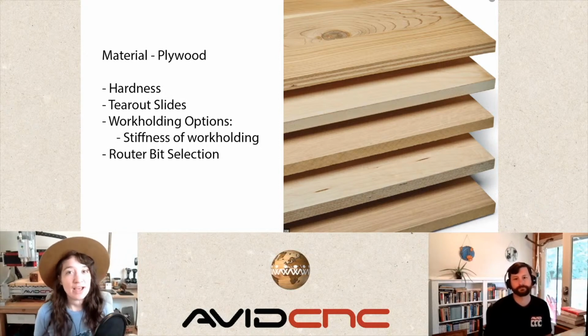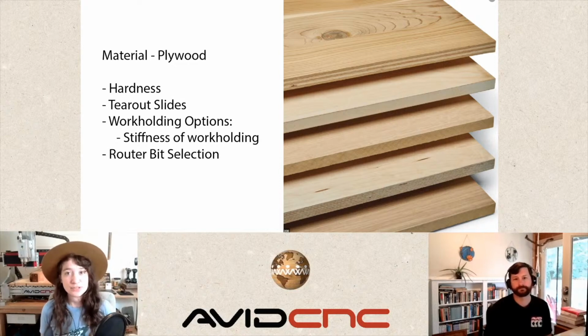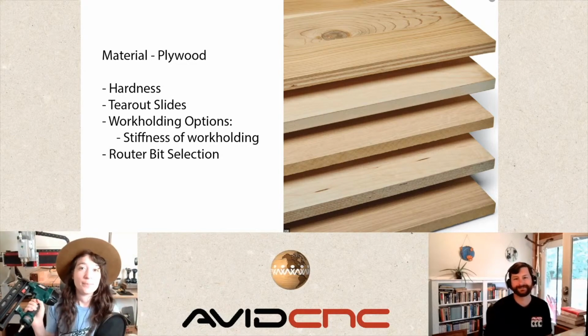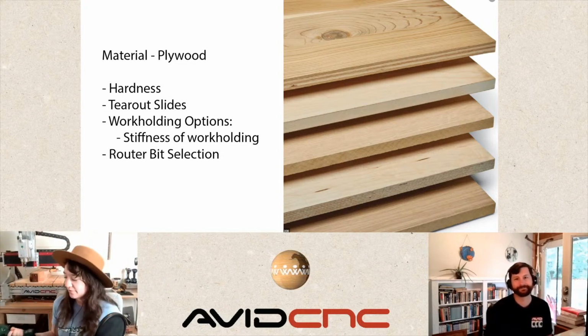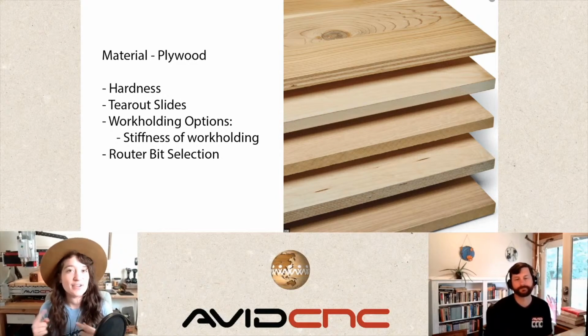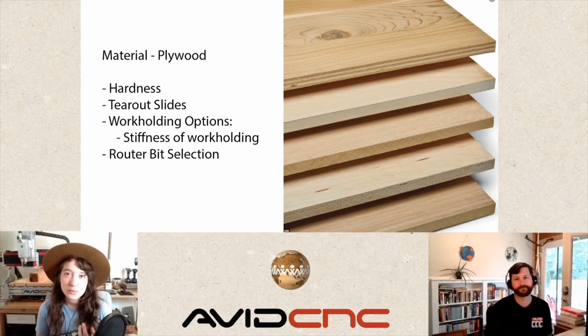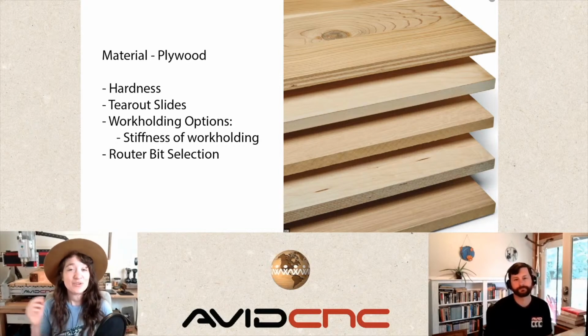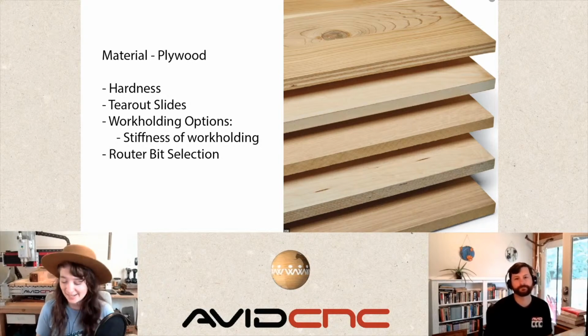We do have a great variety of work holding options. My personal favorite is the Omer nail gun. I use this almost every time I set up the machine, especially when I'm working with plywood. It's my favorite fast, easy solution, and it's very trustworthy. But when you're considering how your work holding is going to affect your toolpaths, we have to consider the stiffness of the work holding, how reliable it is, if it's going to allow any flex in the material as we're cutting. And then the last thing I would say is the router bit selection is going to be very specific in relation to the type of material qualities you're doing. So we'll get into tooling in a second, but here we go.